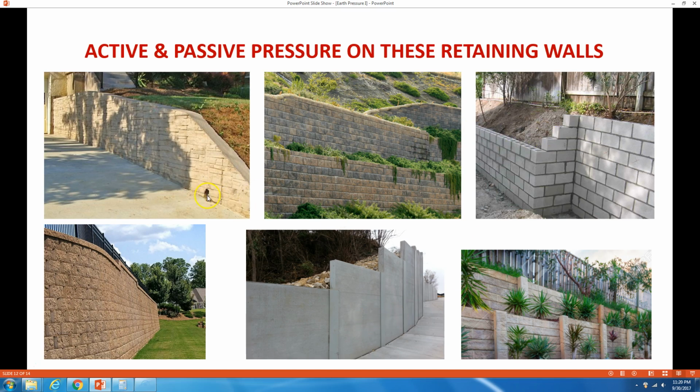This particular one has a V-pole. And passive resistance, you cannot see it, it's buried. So it's providing resistance in the footing, in the buried footing portion. The same thing here, the same thing here, the same thing here. But here, this will be an embedded retaining wall or a soldier beam wall, and the embedment depth is usually 1.3 times the retained height, and that's where the passive resistance is applied. And this would have it under the buried footing section.